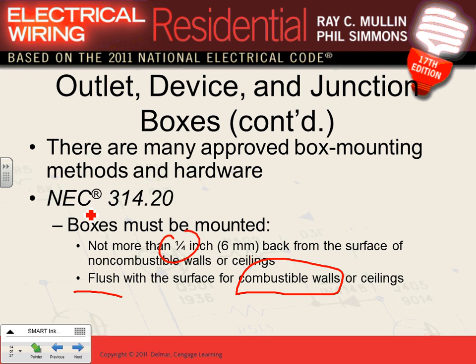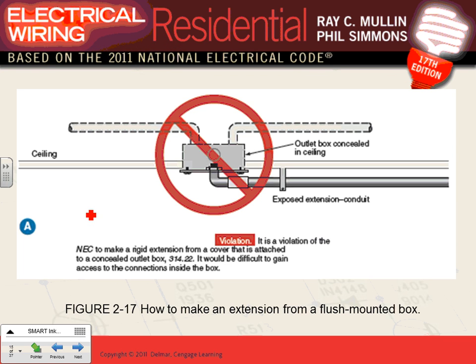So keep this in mind. Who cares? Since you guys are designers, it's great when you're a project manager to know all this. Wouldn't it be really great to look at all your project, guys, and estimate your project and check your work before the inspector walks in and pinpoints it for you? So knowing all this, the sit back is a good idea. Why? Because we're going to be inspecting your own work. Any comments, guys, about sitting back the boxes? Flush with combustible, sit back no more than a quarter if it's non-combustible.